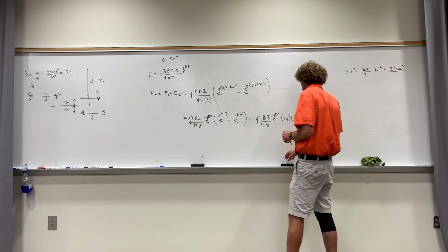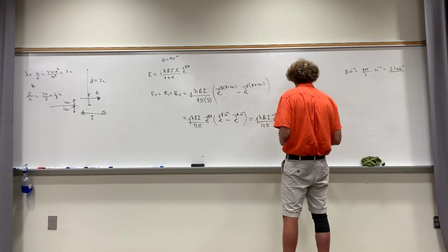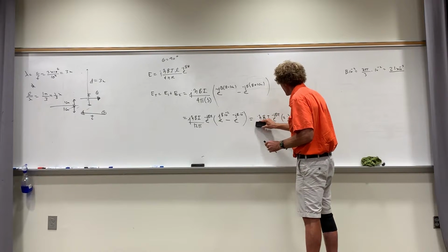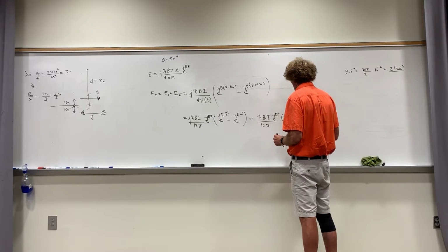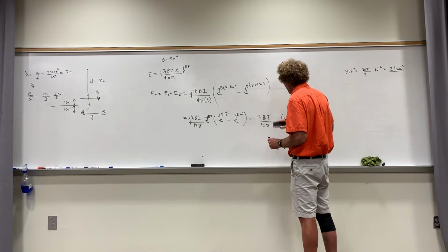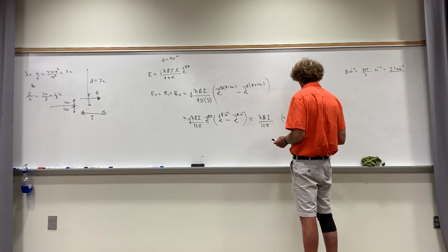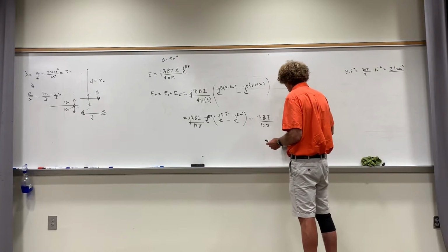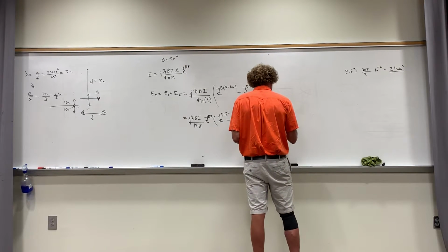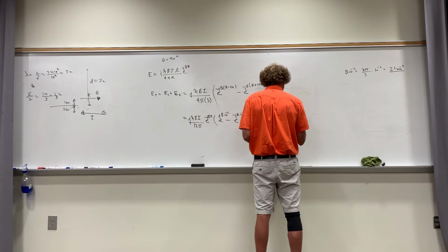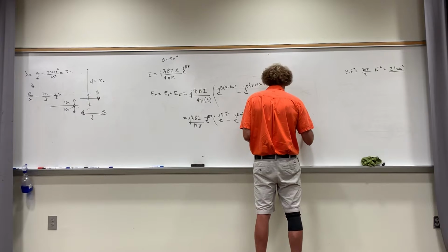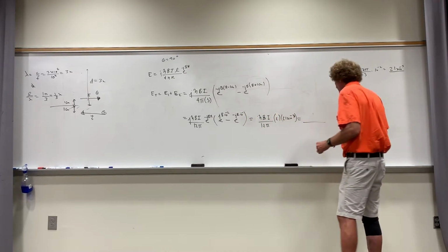So now you can simplify this whole thing. I can simply get rid of the j here and j here. I know there's a negative sign, but don't even worry about that because it's magnitude. I can get rid of this e to the minus j beta r because that is a phase, right? And then this sine term doesn't even need to be here, just beta times that. So really what I'm going to do is this. Say it's that times 2 times 21 times 10 to the minus 3. And that should be the value of the total electric field.